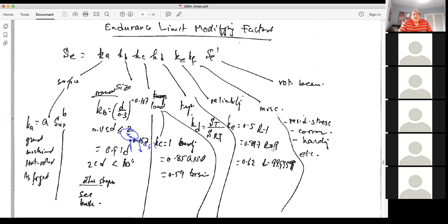And if you accept different levels of probability, then reliabilities, then you can use a larger fraction. And then the other factors depend on whether you're working in a company that has its own experimental data. Then you have to put that data in a format where you have a factor depending on the corrosion or erosion or any of the environmental effects.